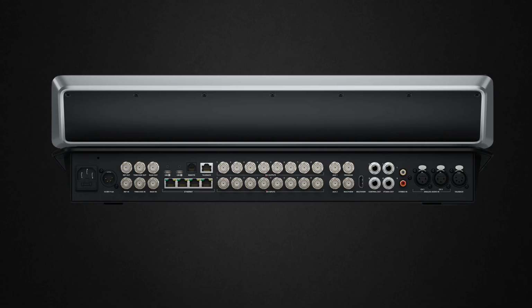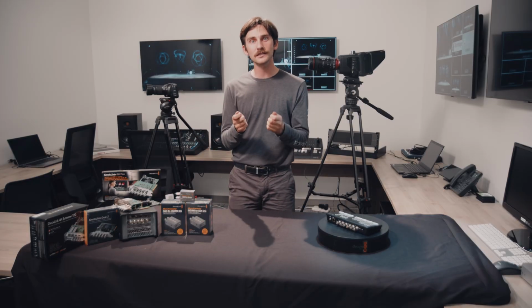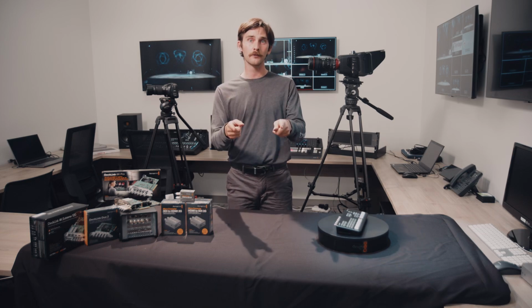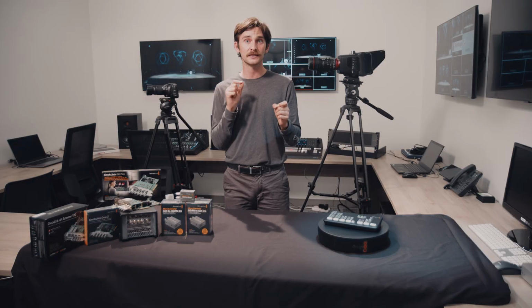Except for the difference in resolution, the Television Studio models all offer 8 SDI inputs and 12 outputs, 10 aux, and a dedicated multi-view and program feed. You may be wondering why you need quite so many outputs, even more than you have inputs. The reason is because there is some information you want to be able to send back from your switcher to the cameras. Like I mentioned earlier, color control information for your compatible Blackmagic camera can make each of your cameras provide a consistent image, and a program feed back to your camera operator for them to be able to see the graphics layering or the angles of the other camera operators.